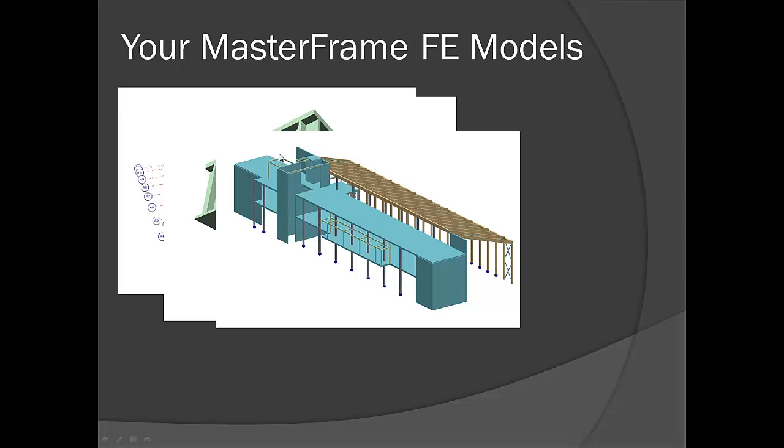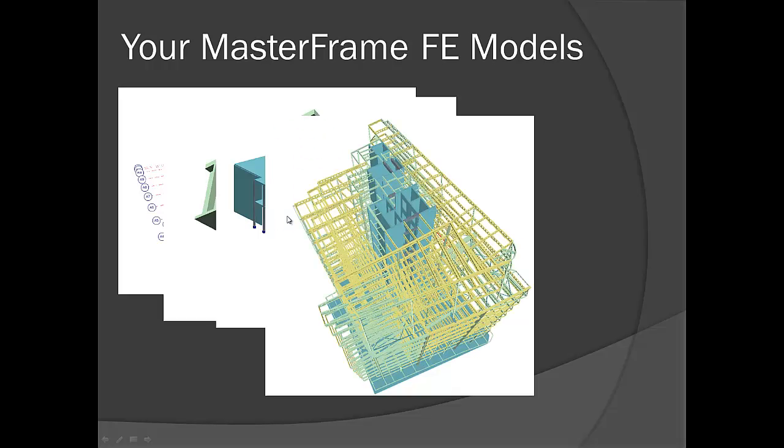Another flat slab structure with a mixture of timber, steel and concrete and slabs and walls all in the one model. Quite a complex structure here, with a really intricate system of shear walls with openings modeled using the finite elements, laterally supporting a composite cellular type structure. And actually down at the bottom of this structure we have a finite element floor slab modeled at the base as well, which may indeed be a pile supported raft or something like that.